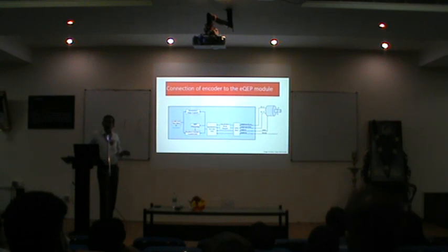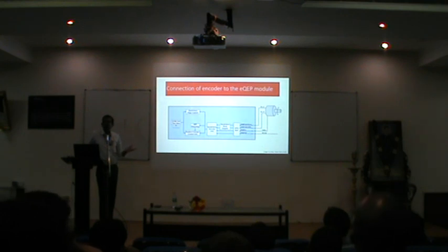Imagine you doing the same thing all by yourself. You receive the QEP pulses just to sense the direction. You count the number of pulses through your program, of course. You write an instruction to count the number of pulses. Then you manipulate that information: total count divided by 60, times seconds or minutes. You count it, then you produce a result. That result you feed to the control algorithm. See how complex it is? So these kinds of peripherals are there for making our system design tasks easier. The only thing is, we have to identify them and start using them appropriately.